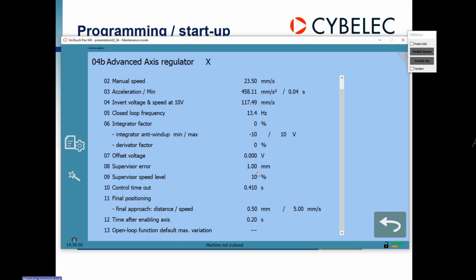If you have a mechanical issue in your gauge and you cancel those parameters, then the gauge will start to move forever and will never stop moving. So I advise keeping those parameters. And if you get this error 32, 33, or 39, check out the parameter manual.